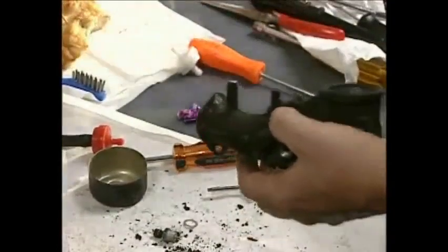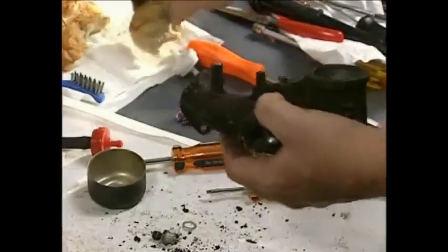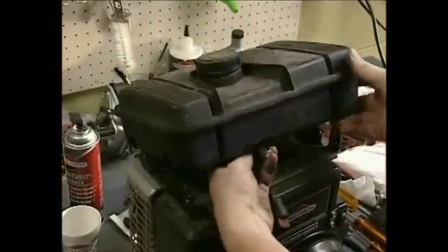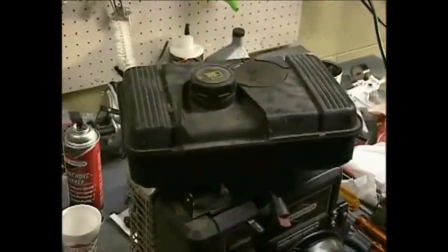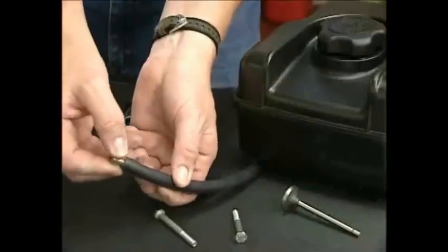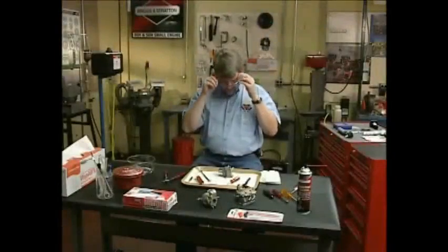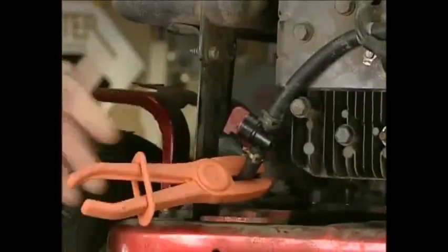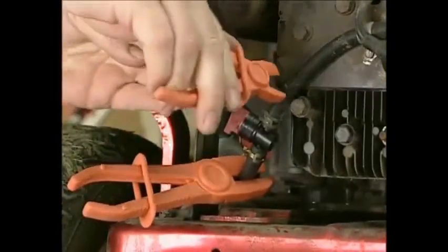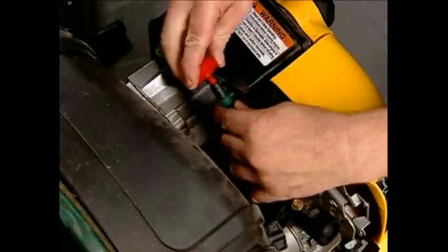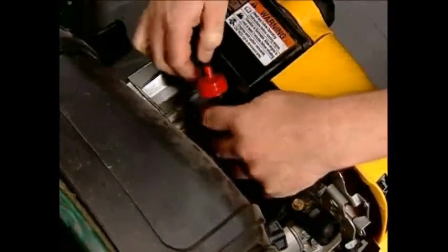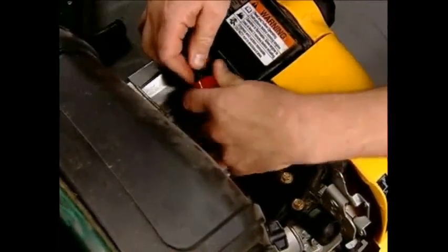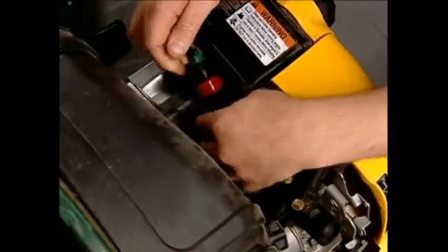Non-professional servicing practices such as dirty repair benches or using bolts to plug fuel lines will cause dirt or debris to enter the system. It's like a surgeon who doesn't wash his hands before an operation. A carburetor repair bench should always be kept clean. Fuel line clamps should be used when disconnecting any fuel lines. Fuel filters can control some of the dirt and debris that enters the fuel system during equipment usage. Briggs & Stratton has always offered a fuel filter with its engines.